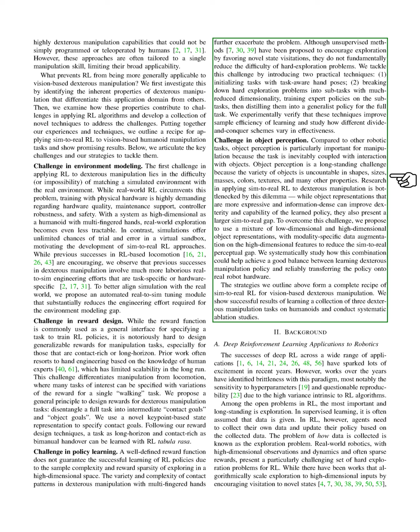The fourth challenge is object perception, which is crucial for manipulation since it involves interacting with various objects. The vast diversity of objects in terms of shape, size, and other properties makes this a long-standing issue. The application of sim-to-real RL in dexterous manipulation is hindered by the need for expressive object representations, which can widen the sim-to-real gap.